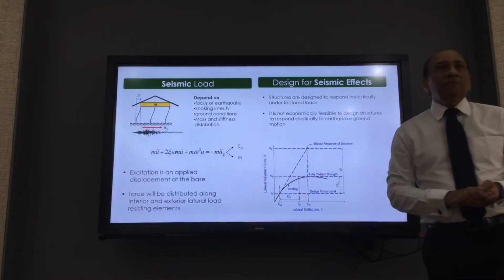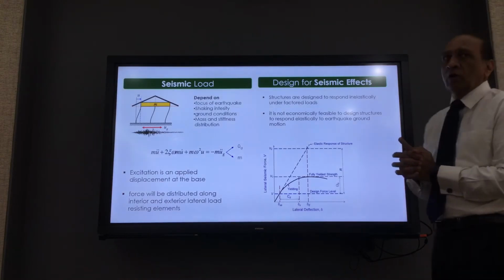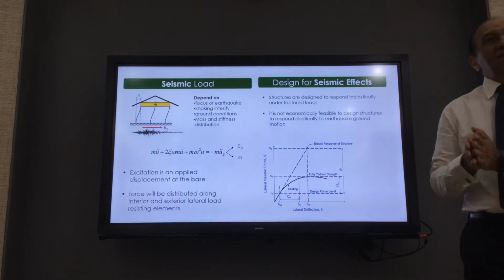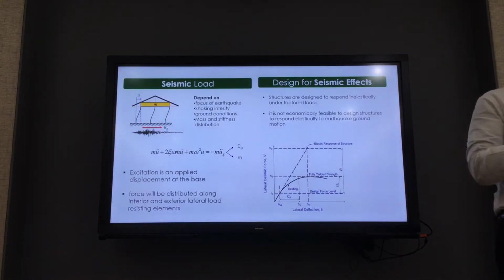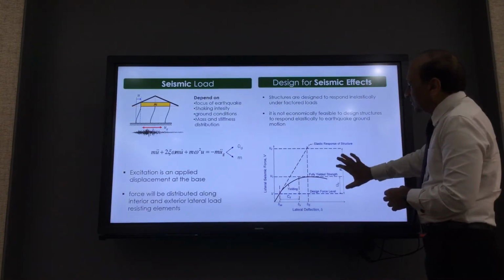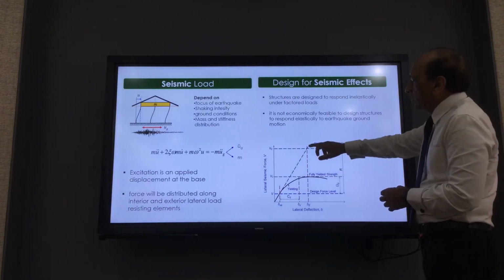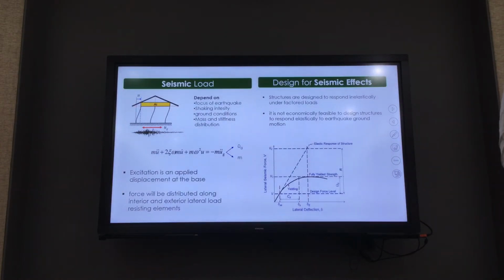So the first thing that I want to emphasize, I have mentioned this before also, is why the performance-based design, especially for tall buildings, generates a better result, or better, I should say, confidence level than a traditional design. One of the important factors for that is this concept of converting or estimating the nonlinear response from linear response. Because we are not able to do that pushover curve for each structure, the building codes try to estimate it.